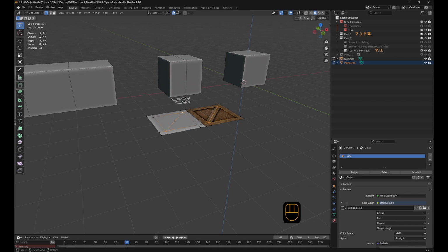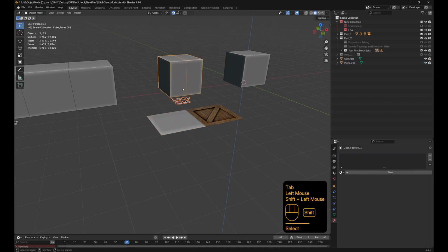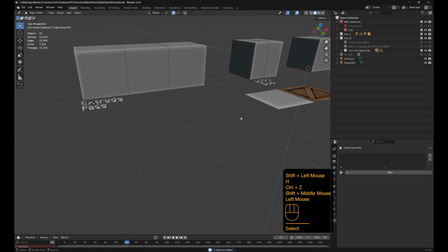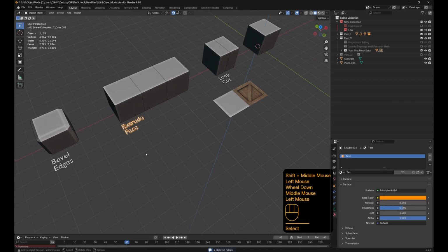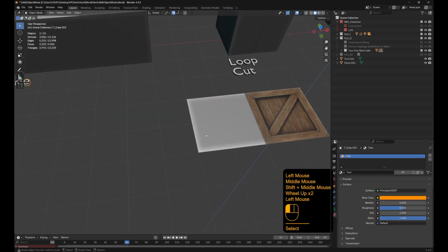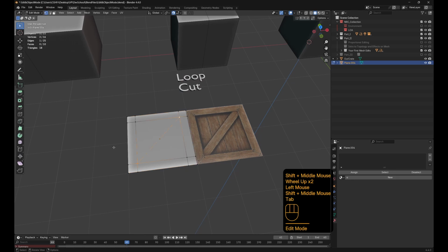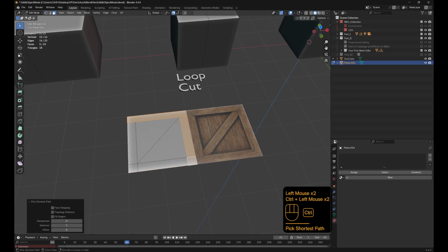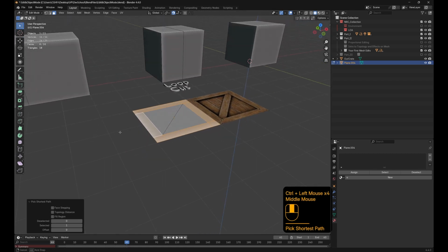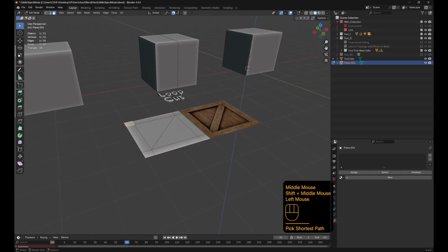How do we bring these shapes out? Well, we've just done that, so let's hide loop cut. Actually, I'll leave that there for you to see. We'll use Extrude Faces next. Now, what's extruding? If I come into edit mode, come up to face select, and let's choose these to start with. I was just holding control then, so there is a difference.